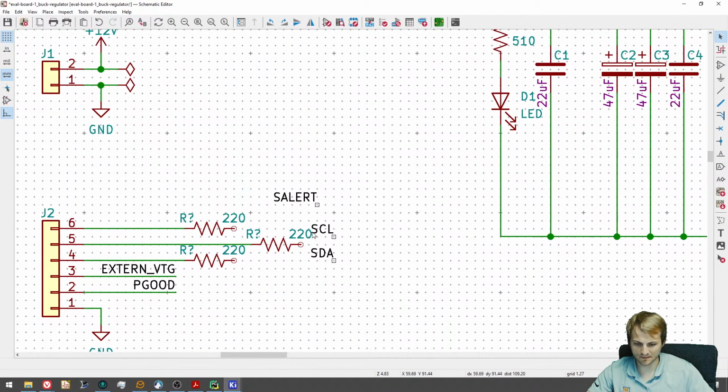But I squared C is pretty tightly limited on what the maximum bus capacitance is. I don't remember off the top of my head. It's like 470 picofarad, something. But that's actually kind of bit me before. I'd forgotten about that and tried to do it to filter it.